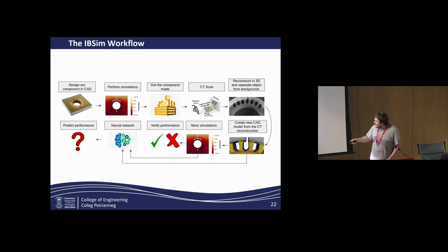Does this work? It does, yes. You design your component in CAD as you would normally. You then perform your simulations based on that to get your baseline and say, has this model been well designed to work, and you get temperature out, pressure out, whatever you're looking for really. You then get your component manufactured, take it off the assembly line, and perform a CT scan.